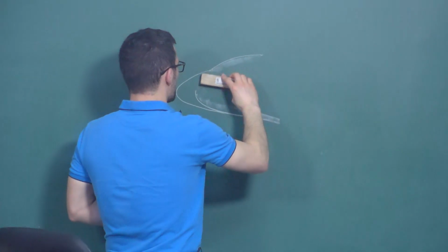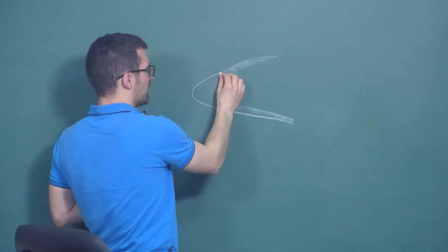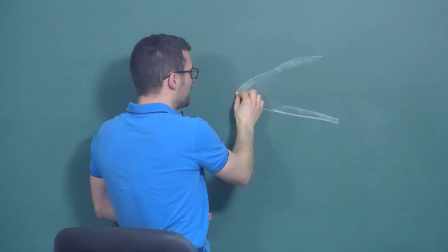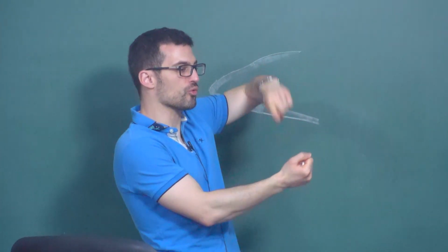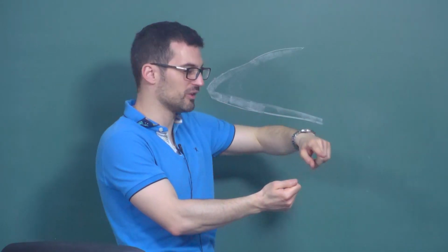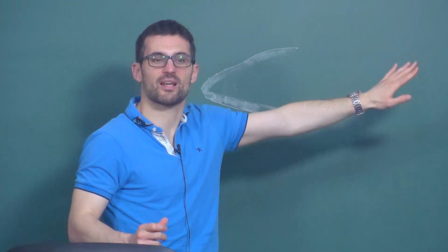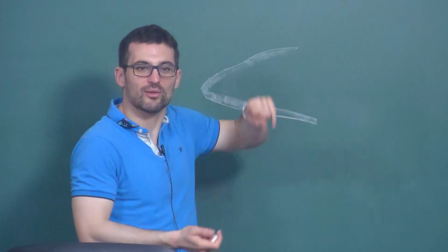You rupture the film, get more corrosion, but again, you quickly start forming the film again. But now it's like you're applying a new paint. So this new paint has never seen any applied load yet. It's a completely new paint. So the cyclic process starts again. So you're doing an experiment where you progressively increase your load, you rupture a film, you progress your corrosion front. Now you are depositing a film again, but this film hasn't seen all the history before. It's like you applied a new paint. So the counting of the critical strain starts again.